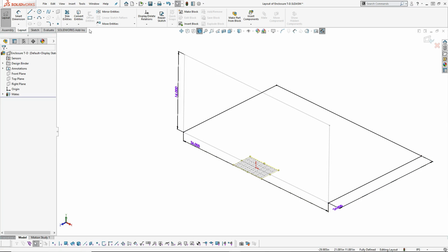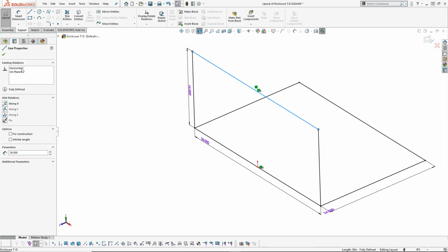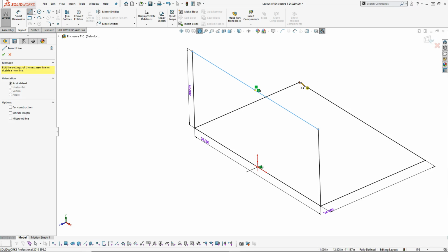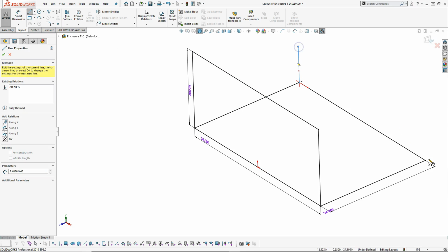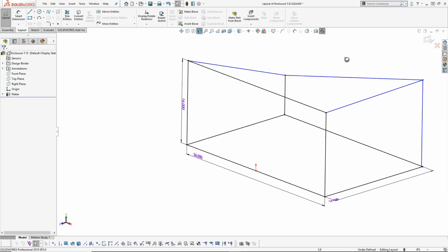Right. And let's see, I had a vertical, we had that on the top, so we can double click, everything becomes apparent. But when I pick on these, we're going to see that horizontal on plane. And again, that's just helping with the rotation, so that things aren't going to get all weird before we get a chance to get this fully defined. Alright, so got those. I'm going to go ahead and connect the dots. So even that floating origin, as long as I'm connecting point to point, it looks like I missed that one, it's not going to have any issues.